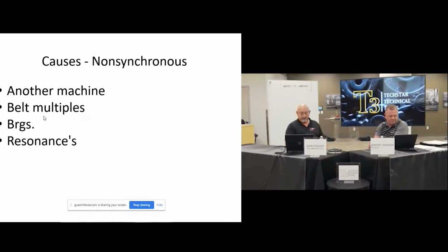Gotcha. And those typically on the bearing data sheet, a lot of times it'll have those fault frequencies on there for you, correct? Yeah, you can go to a manufacturer of the bearing and get that information. You can also, people out there have databases. Sure. They'll have like every bearing known to mankind with all their frequencies in it too, that you can get.